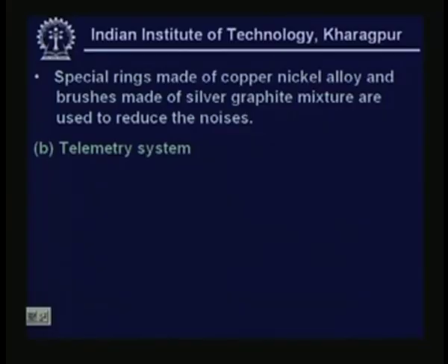Now, special rings made of copper nickel alloy and brushes made of silver graphite mixtures are used to reduce the noises, right. So, you have to use these special types of slip rings, made of silver graphite mixtures, to reduce the noises.